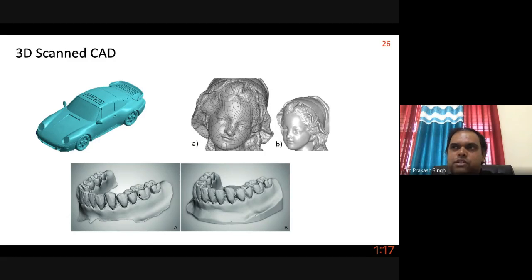So what you do is take the engine of Honda or Bajaj to the scanning room, scan it, and generate the 3D CAD. After the 3D CAD, do some pre-processing, which I'm going to tell you how to do, and then do the modeling. And you also do the modeling of our own design. Since you have already designed it, apply the same boundary conditions. And you used to see sometimes that, oh, they have given some special feature for air passage throughout the inside of the engine, which we have not given.